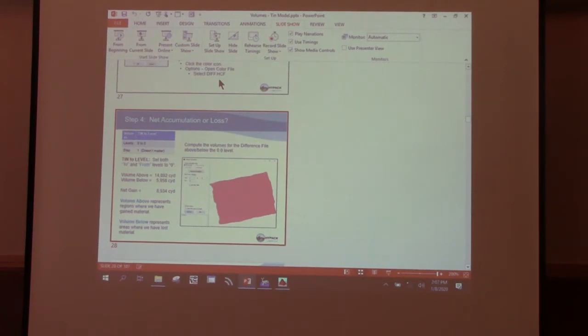And they'll say, we're just going to take 2 feet out of this lake. Everywhere in the lake. We don't care what the depth was. So we take the surface and we offset it 2 feet. That becomes the template. So over there we might be taking it down to 14 feet, and over here we're taking it down to 8 feet. But it's not a slope from 8 to 14. It's a variable surface that you're trying to cut out.